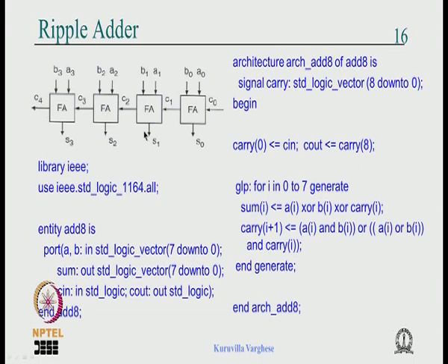Now, as you are taught, the carry lookahead adder is derived from here. The basic idea in a carry lookahead adder is that when it comes to this stage, instead of using something already defined, this stage will work with B1 A1 B0 A0 Z0 to generate both S1 and C2.